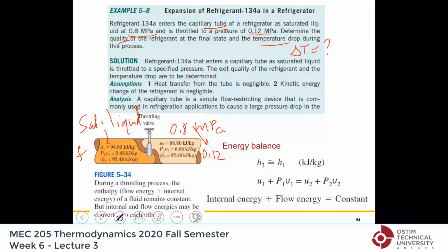Okay. Now, energy balance, throttling device. No mention of kinetic energies. Heat transfer we can neglect. Work there is none. Okay, potential, don't even mention it.